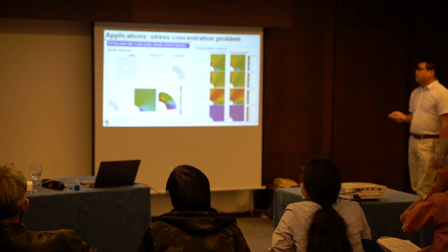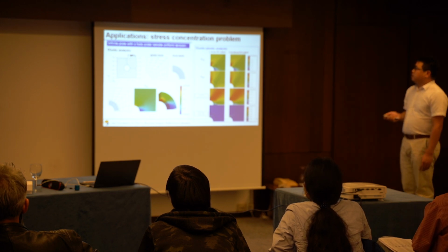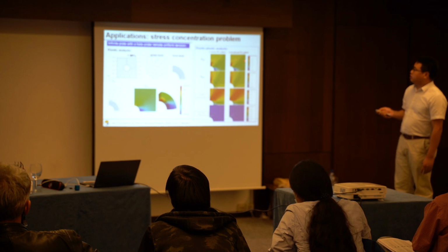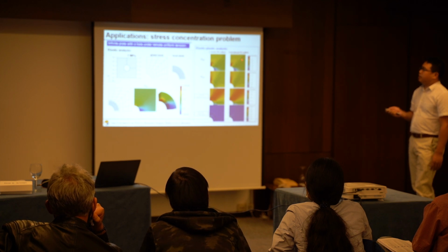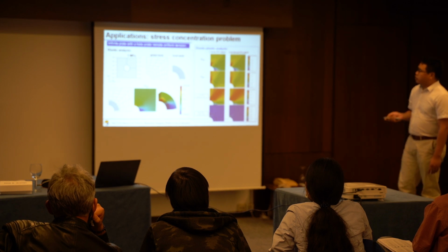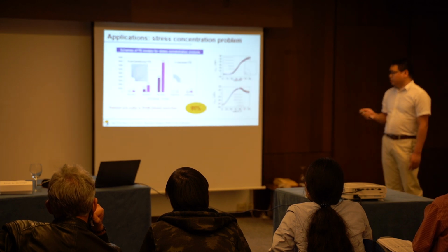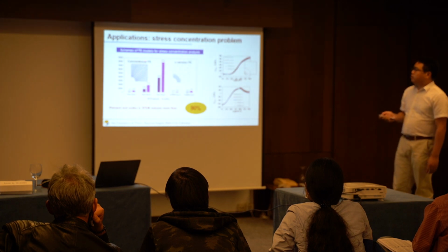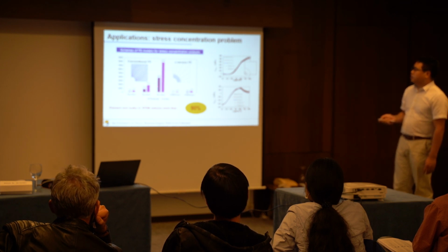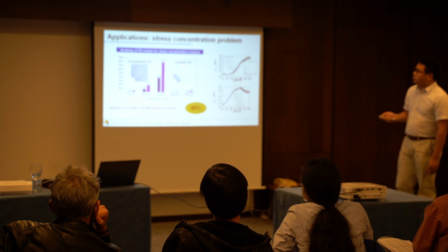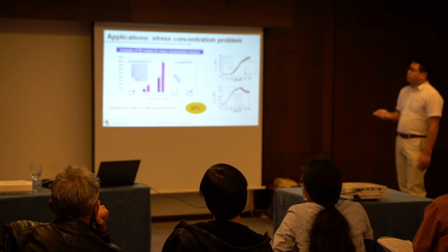We also perform the elastic plastic analysis, and this is the result from the conventional finite element method with a very fine element size. We can see that the stress field and the strain field look very similar. We compare the accuracy of this method with the conventional finite element method. Here I present 3 sets of finite element calculations, with the number of elements and loads presented here, as the element size decreases. We also present 2 sets of calculations from the SFEM.